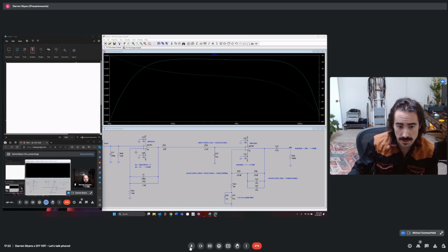So these capacitors are running fairly close to the inverting input on U4. Some people put a little isolation resistor to isolate the feedback coming back, because this trace will be longer, and so you do have to worry about how long this trace is as well. But you're better off reducing the length of your virtual ground trace and then just optimizing this.